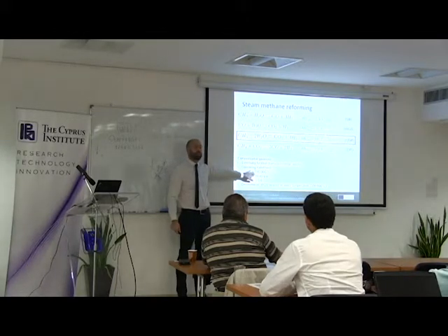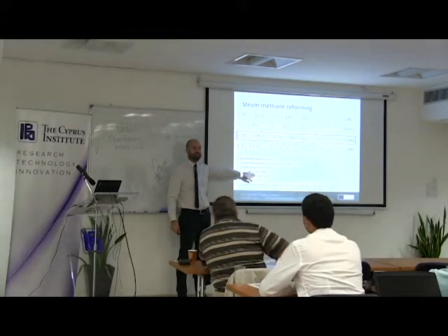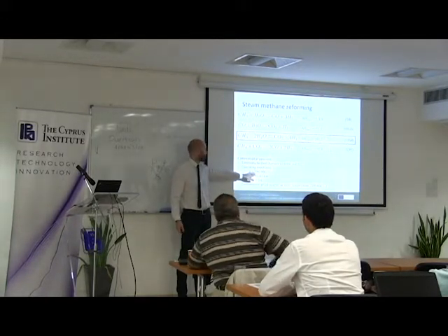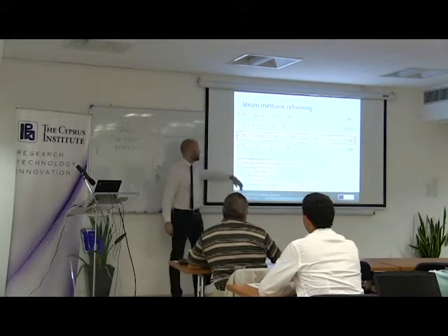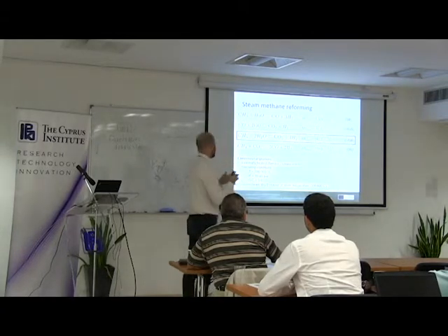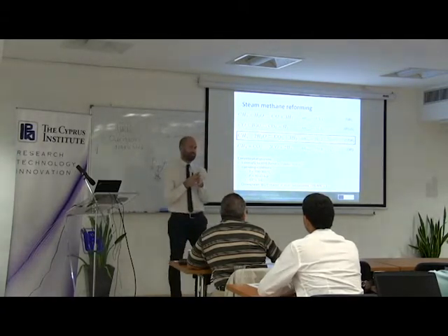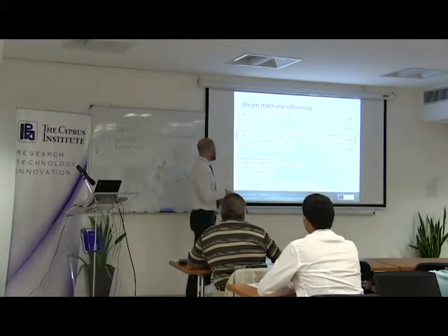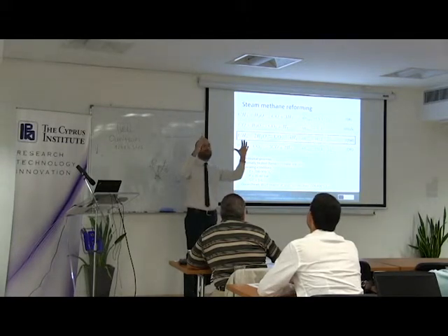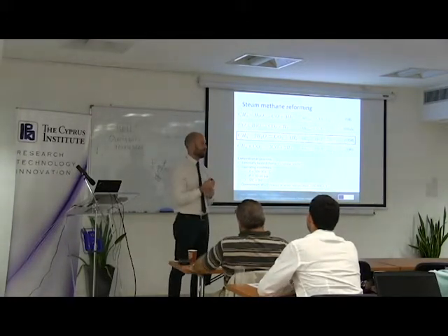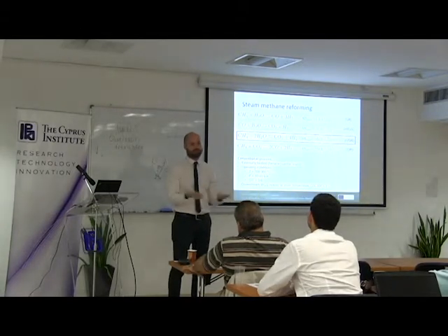This temperature means, can we use a Fresnel system to attain this temperature? No. Can we use a parabolic trough? Not even. Today, even if there are some studies to prove it, we must use a point focusing system, typical of solar tower, because the dish wouldn't have the necessary capacity to have a convenient process. So either we do it directly, putting the reactor on the focal point of the receiver, or we have some intermediate heat exchange fluid, basically air.